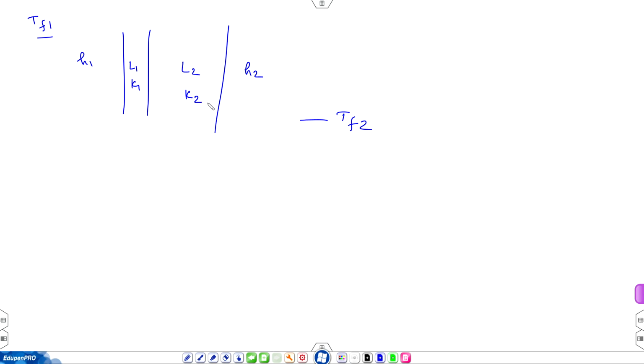So, linear variation in slab 1, linear variation in slab 2. What is the variation in the fluid region? You do not know, because the entire heat transfer process is contained in a single numerical parameter called h, but you know temperature is decreasing. That means, if Tf2 is less than Tf1, then the entire heat transfer is from the left side to the right side.